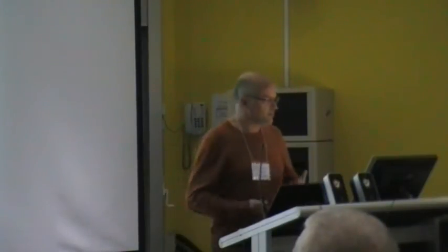Once we've got the thing going and it works and we've met some of these goals, then we'll decide where we go next. Do we miniaturise the thing, or do we put some other product in a box? We're not really sure at this point. So we'll wait till we get it going for that. Where we're at after a couple of weeks is we've got FSK transmission and reception going at the 10.7 megahertz IF point. So we can transmit signals, receive them. We're getting pretty reasonable performance.